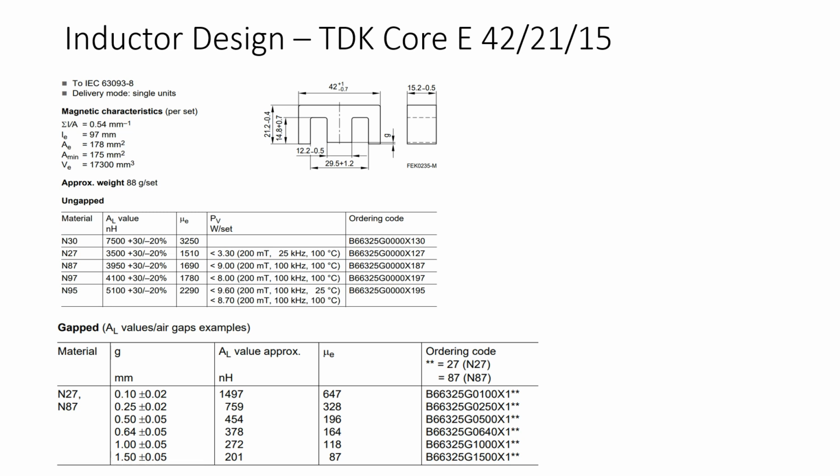But for applications in which the inductor is not continuously running, it is running with a particular duty cycle, then we can also use, for example, this value for 400 kilohertz if the operation is not continuous, as in our case.